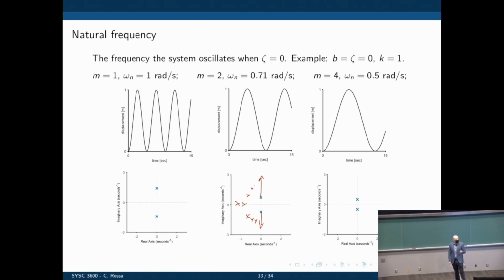And that's to say, once again, that what dissipates energy here is the damping ratio, which is related directly to the exponential components. And so far, for everything we did, we ended up with poles. If they have a real part, the real part is negative.